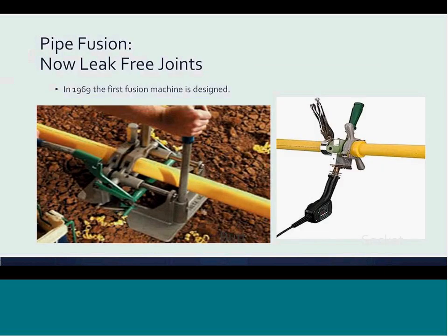The fusion of the pipe connection for direct burial applications reduces the opportunity for leaks in the ground loop. There are different types of fused connections approved for ground loop systems: socket, butt, and electrofusion, for example. Each type of connection requires different tools. Some connections, such as socket, are more cost-effective and easier to install on smaller diameter pipe, while larger diameter pipe work requires butt or electrofusion.